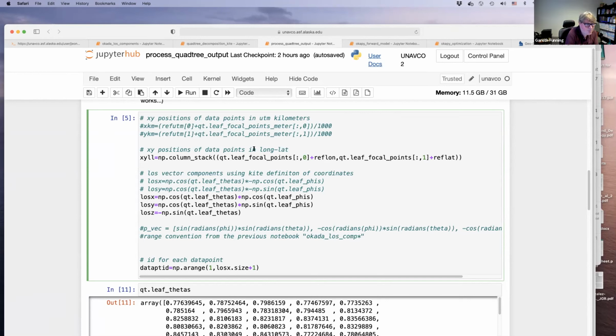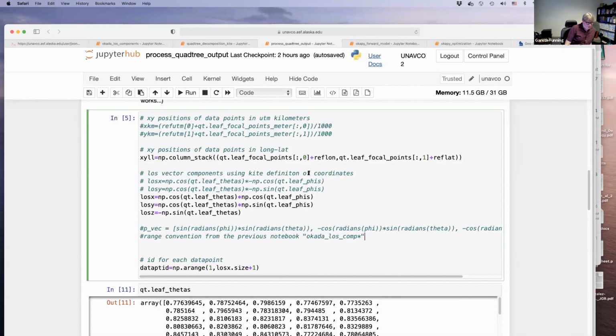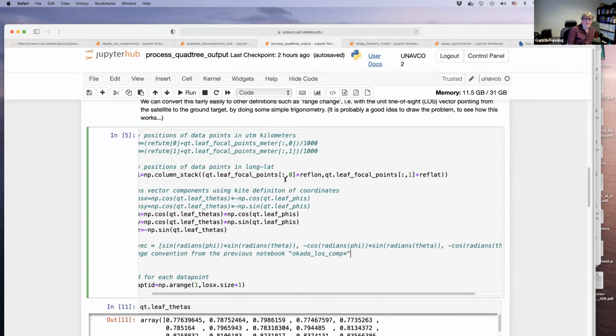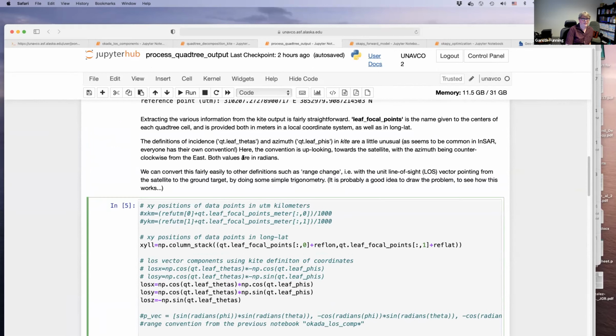Okay, so your interferogram should be in range change if that's correct. So Gareth, I was thinking there's a step prior to this where he defines the geometry that perhaps was done for ascending rather than descending. Is that true? No, what happens here is that Pyrocko reads the LOS file from the data itself. From the data processing, yeah. So it should do everything associated with getting the azimuth and incidence information correctly. Interesting. Okay.